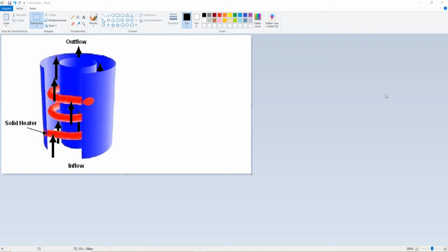The material parameters that we're going to use for this calcium carbonate deposit are 100.87 kilograms per kilomole for the molar mass, 2.71 grams per cubic centimeter for density, 0.9 joules per gram Kelvin for specific heat capacity, and 3.85 watts per meter Kelvin for the thermal conductivity.